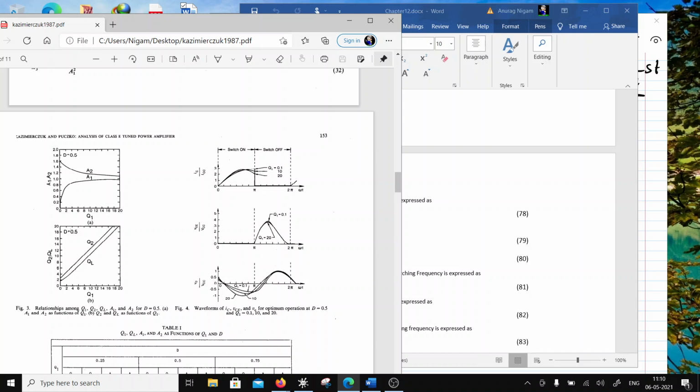These are going to become asymptotic as you increase Q, and they will come close to f0. But still there will be a residual because of this reason. This is versus Q, for a given duty cycle. Now this algorithm doesn't place any restriction on duty cycle or any restriction on Q.